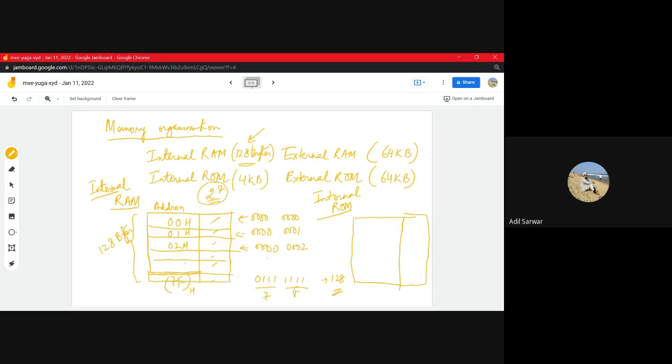Okay, so 8-bit data here and 16-bit address. Now 16 bits are required. Now 4 KB. How much memory will it take? This size would be 4K bytes. That means 4K memory addresses, not 1,000, 4K memory addresses are there. We cannot use 8-bit now. We have to use a 16-bit register, but not all 16 bits would be occupied in the address.